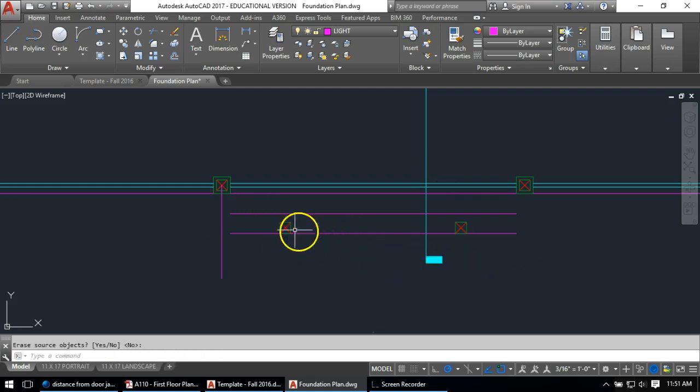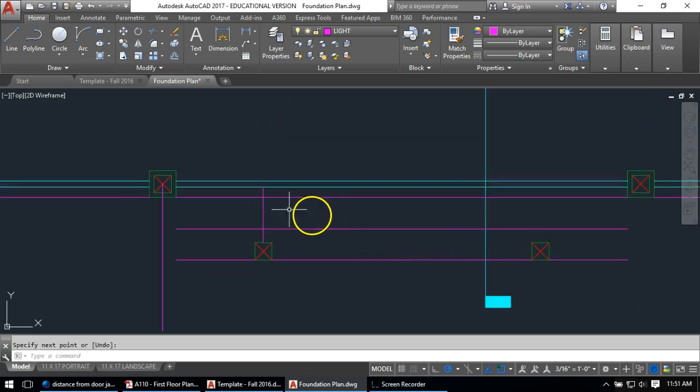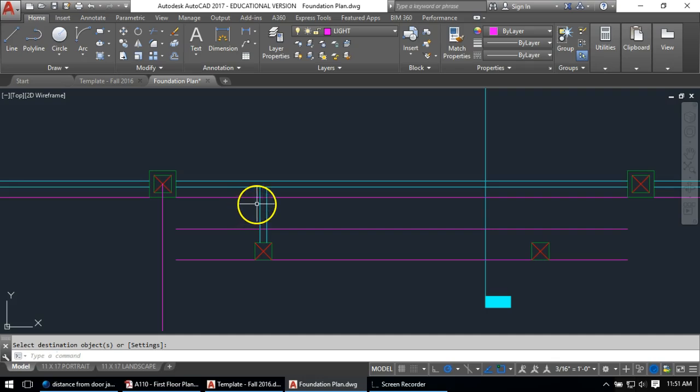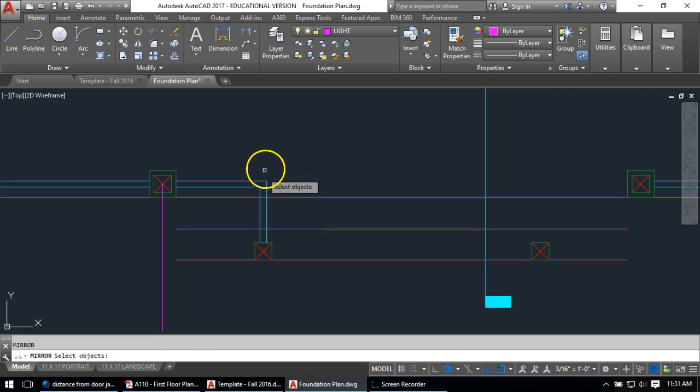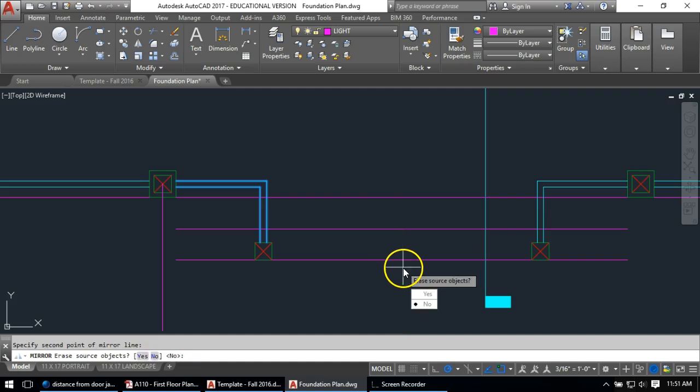I'm just going to mirror it, put it there, and then I have to draw the railing up from the center point. Draw that line there, offset 1 inch, erase this line here, match this here. Since I'm going to mirror this whole thing, I'll just fillet those together, and I can mirror the railing to be that side.